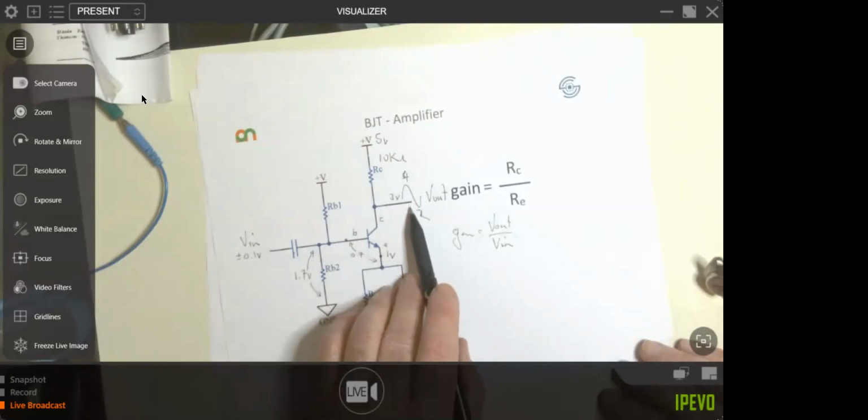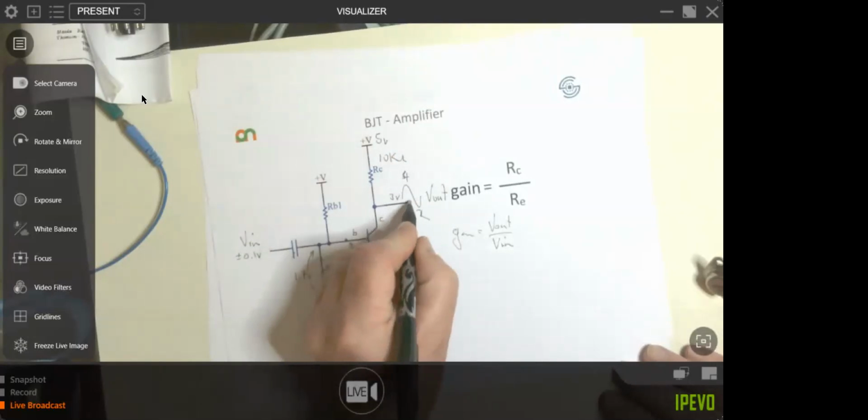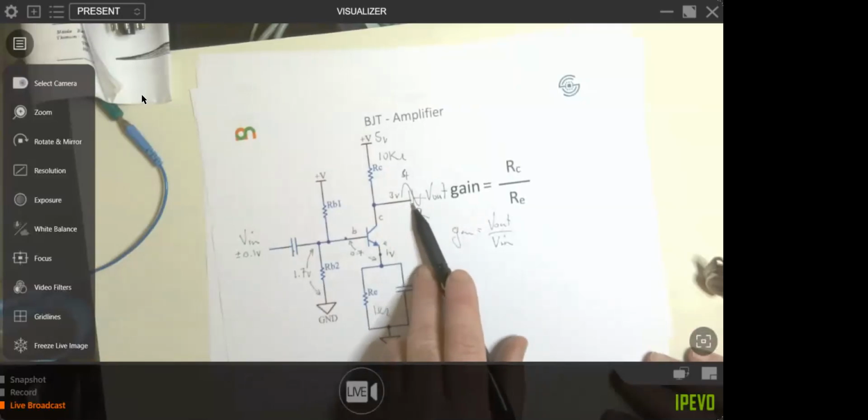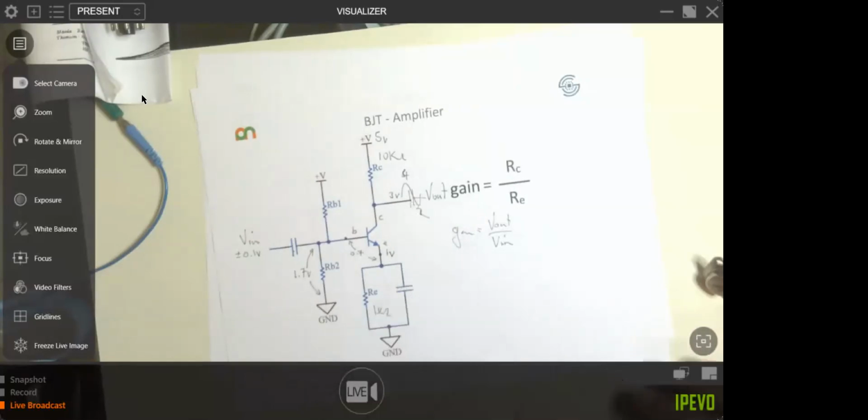You do see, when you look at these circuits, a capacitor on the output. But if you do that and then put it into your microcontroller, you'll be putting a negative voltage into the microcontroller, and that could cause a problem. So if you're going to experiment, whilst you see a lot of circuits with a capacitor on the output, I would probably say leave the capacitor off, so you're only ever putting a positive voltage into your microcontroller.